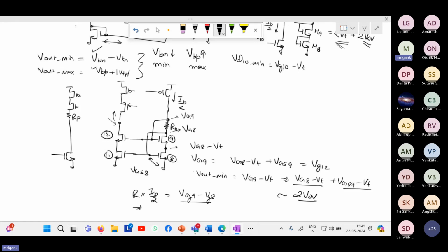Now the same thing you do, you connect it like this, and then like this, and you have the similar biasing for these two. So once again, on the upper side, you will have the similar 2V overdrive minimum voltage, VDD minus 2V overdrive. This is VDD. The maximum output value that you can have, Vout max, will be VDD minus 2V overdrive of P, provided it is biased with this condition that you are trying to ensure that the gate voltages are the minimum possible value.